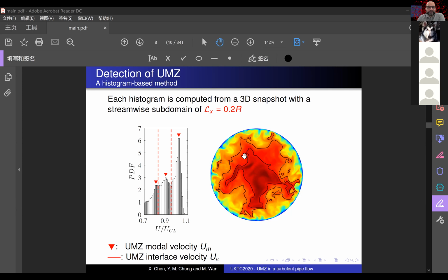Yeah, there are some more sophisticated methods. If you calculate the tensor of rotation and so the vorticity, and you put just one threshold for the vorticity, then you don't have these top shear layers as a continuous line, because the only way of having a continuous enclosed line is by having a fixed velocity threshold like this one. But still you can have lots of elongated structures in the cross-stream plane. And we should see the same results later in conditional averaging. Okay, all right, thank you.